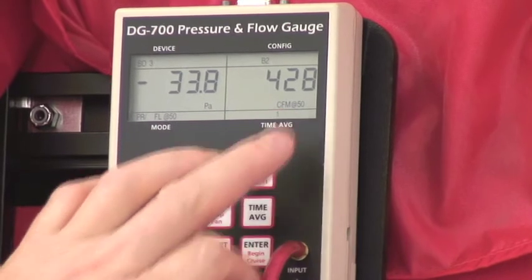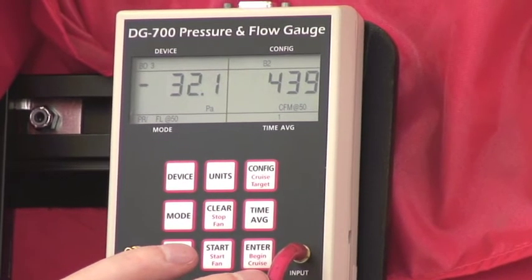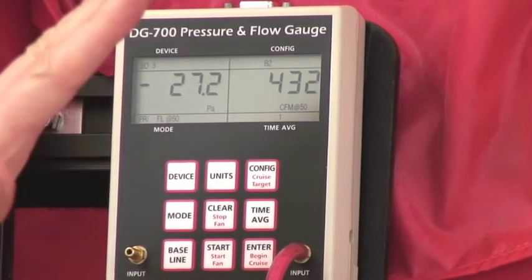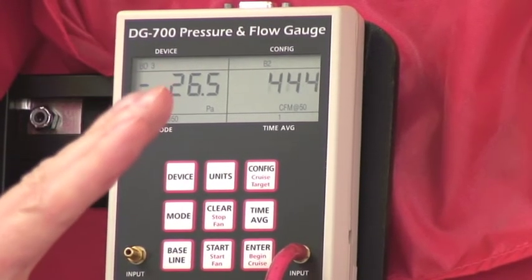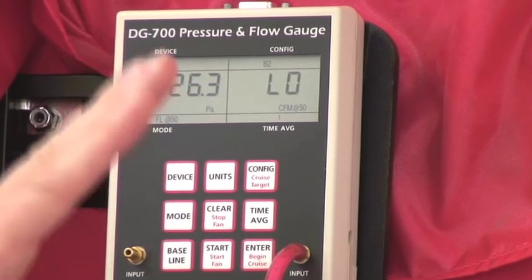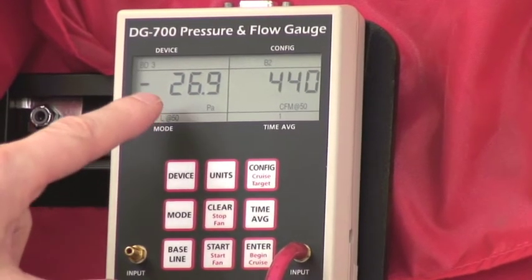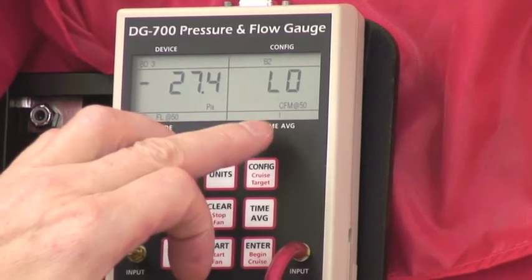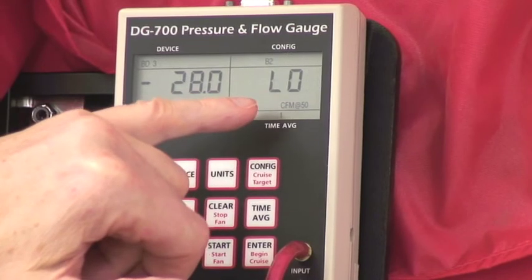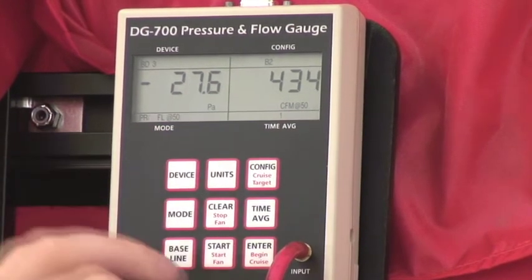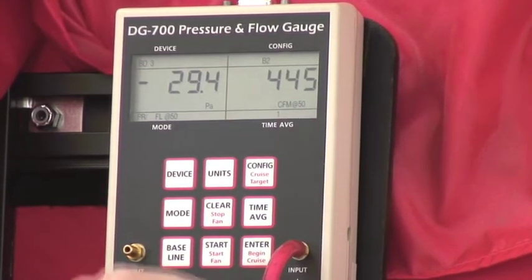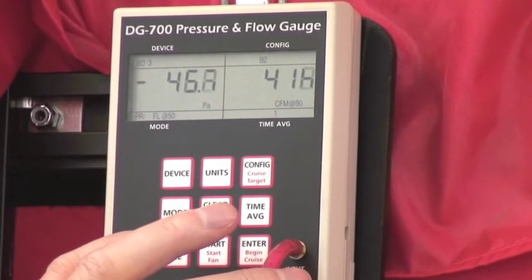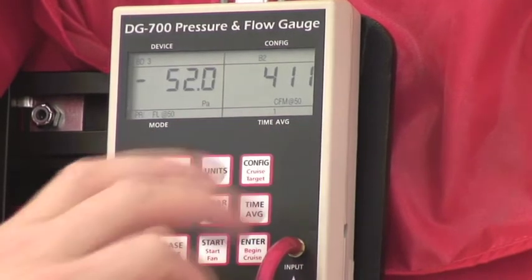Even if the pressure drops, as we're showing here, you'll notice that the CFM is not dropping very much, because it keeps extrapolating back up to 50 and answering the question mathematically, what would the flow be if I was at 50? So even though we're only at 27, we're still extrapolating back up to 50. The fan is running so slow now that our flow pressure is a little bit low. So let's speed it back up again. Notice again, the flow is not changing very much, because again, it's extrapolating to 50 pascals.